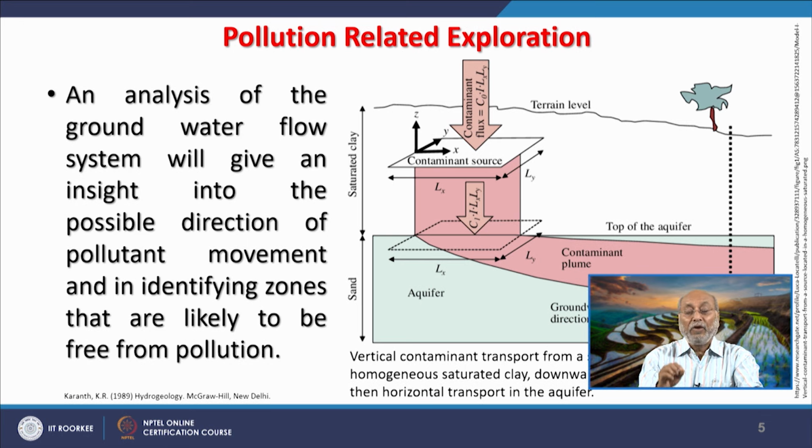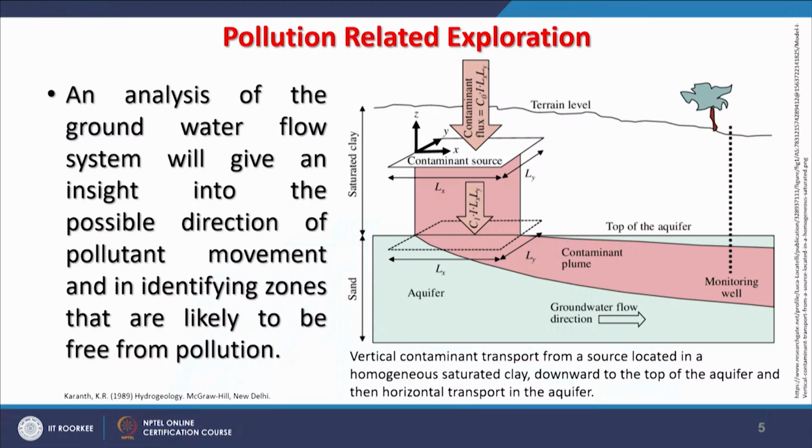These unconfined aquifers are more vulnerable from the pollution point of view. So, analysis of groundwater flow, complete groundwater exploration, is required. How water flows, the pollutants will also flow in almost the same way. So, a complete analysis of the groundwater flow system will give us an insight into the possible direction